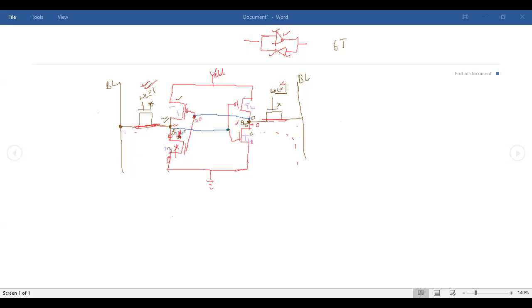So what we do is, here Q equals 1. We want to make it Q equals 0, so here we give the lower potential. Here QB equals 0. We want to make it QB equals 1. So here I attach a high potential source which has VDD equals 1 volt, or whatever voltage you have taken, right? VDD over here. This is VDD.